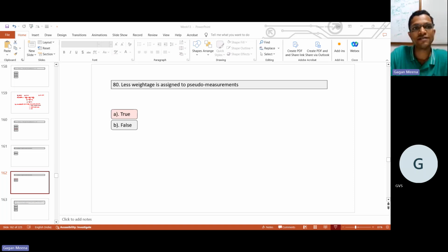You want to find the angle between successive PMU measurements in non-recursive. It is the angle between two samples only. It is 360 divided by 50 samples.